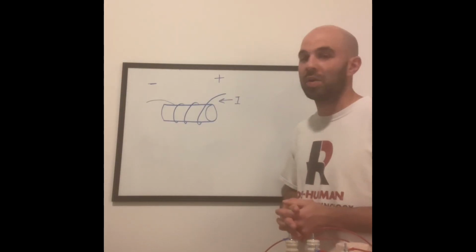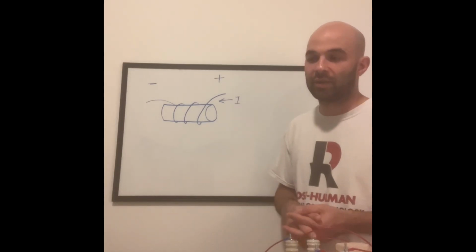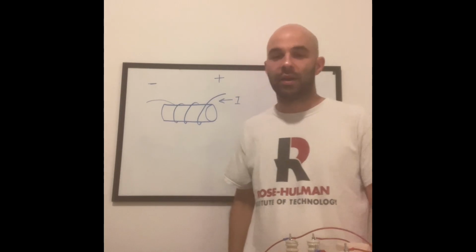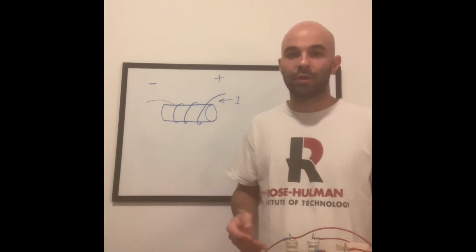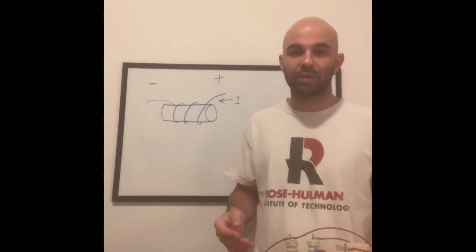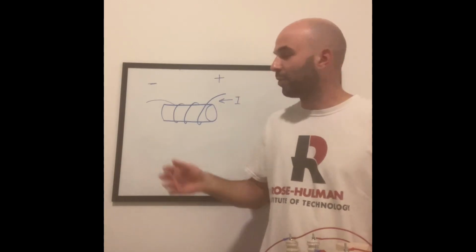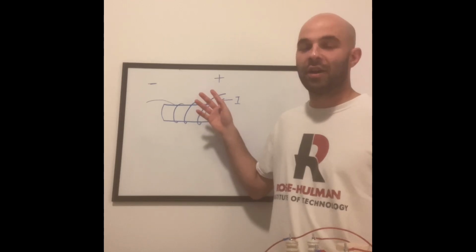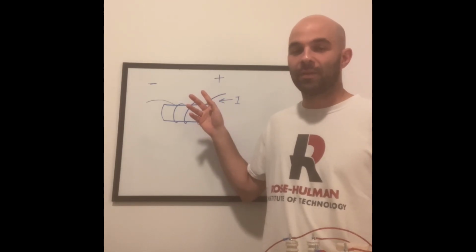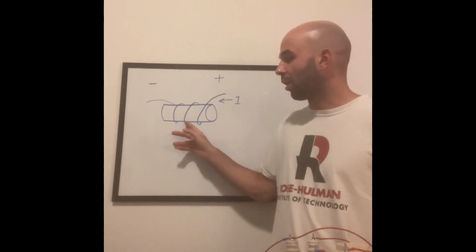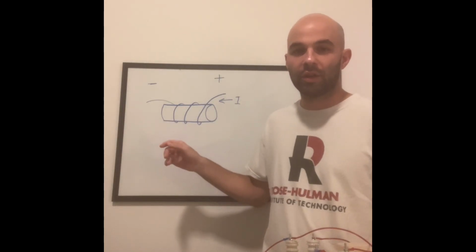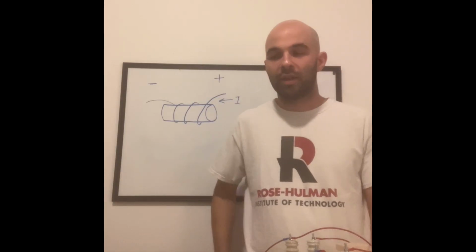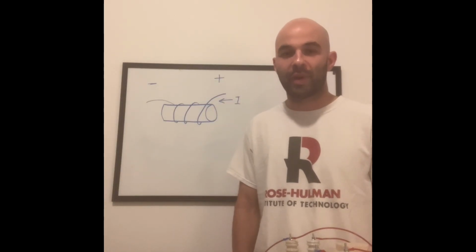So this is pretty much what we want to avoid in our system, because you'll notice that even though you've got your circuit all nicely tuned up and you're able to generate really high potentials theoretically at your output, you may see that you're still getting fairly weak discharges on your terminals. The reason for this is that if you're arcing inside your coil, the energy is not going where it should be going on your output, but it's getting lost. That's something that I see quite a bit on all my systems.